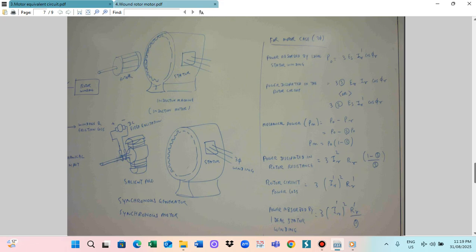So this is the rotor, with two slip rings. One slip ring is connected like this with a wire, and another slip ring with a wire like this. So this is for the synchronous machine, and this is for the stator. Mostly the generators are constructed this way. This stator construction is similar to the induction motor. This is for the synchronous generator or synchronous motor.